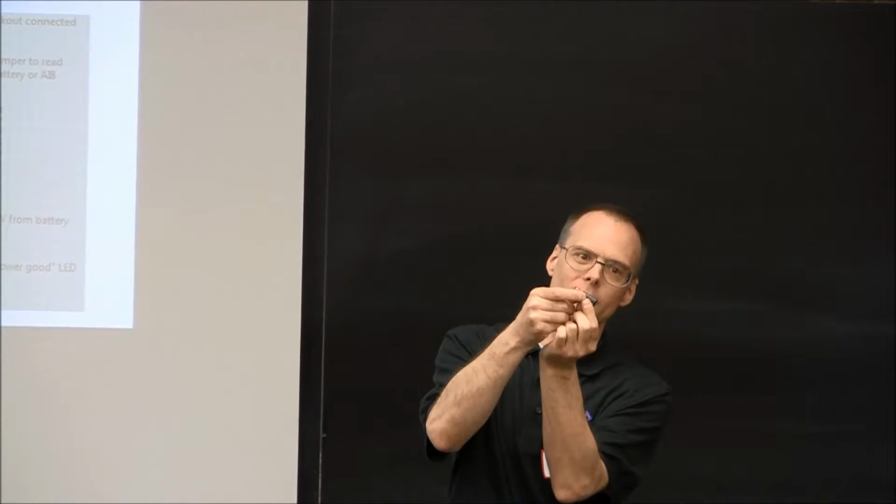Why? What's it measuring? This is a physics one. Gravity. You ever hear people say the force of gravity? It's not a force. Gravity is acceleration. What are the units of acceleration? Meters per second squared. What's gravity? 9.8 meters per second squared. It's an acceleration. So if you put an accelerometer on there and you want to measure acceleration this way, you better get it level, because if you have it tipped, it's going to be adding the component of gravity in that direction.